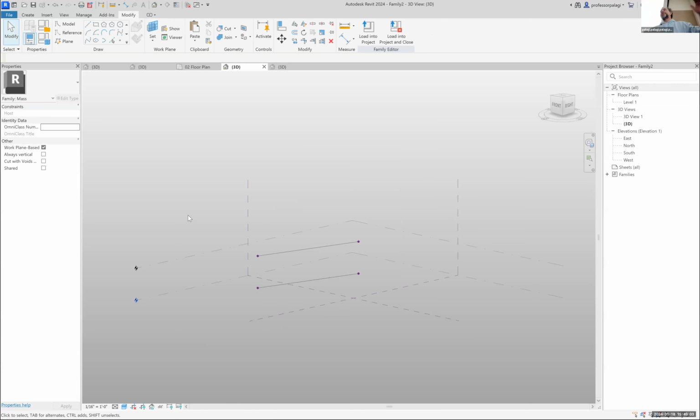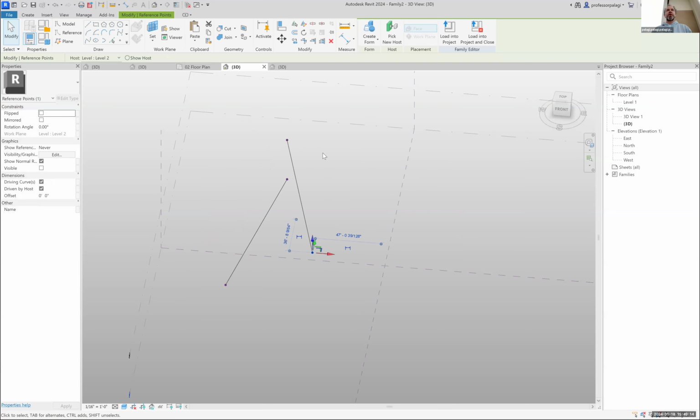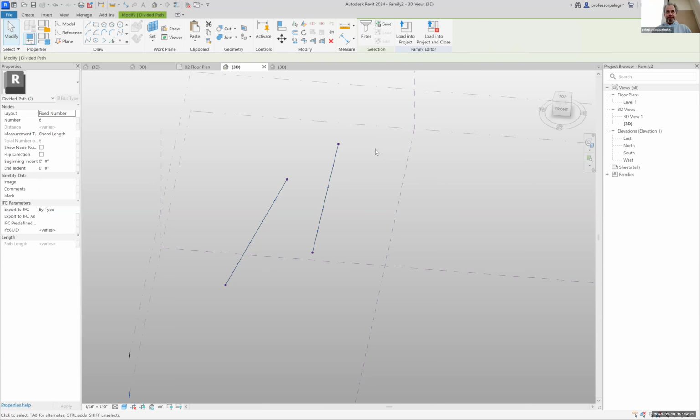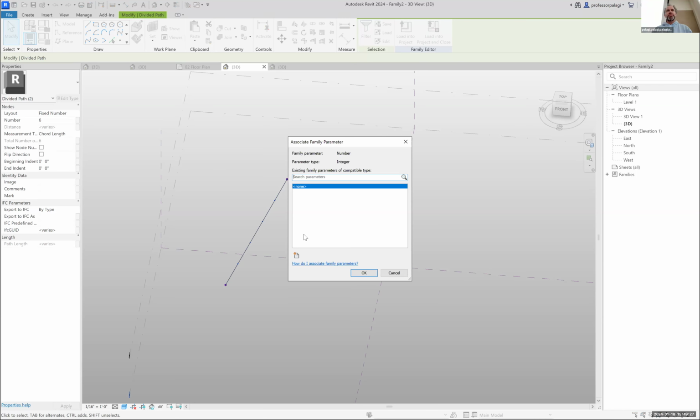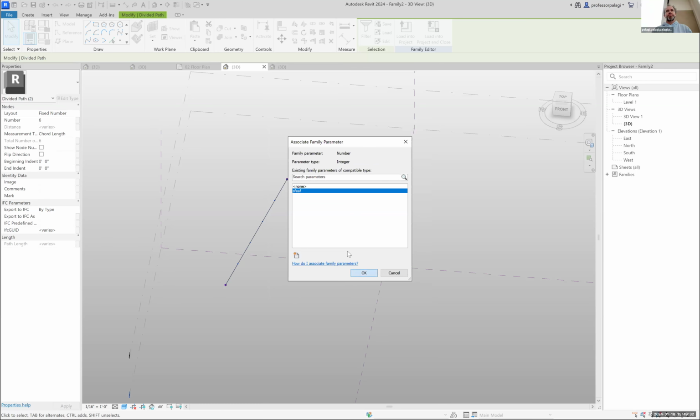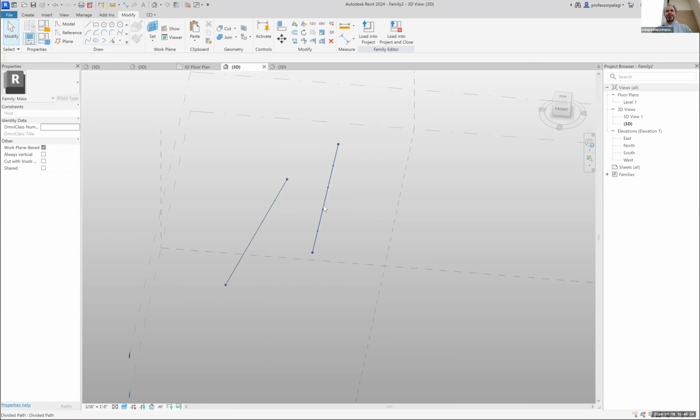You understand, like when you're doing buildings, right? You could say, hey, I want to repeat this on those 30 floors. Like that's how it's made to work that way. Anyways. Okay. It becomes really helpful when you're working out some things and you want stuff to line up the way you want. So nothing more than this. Let's divide the path. I drew them both the same way. Let's make this a parameter. Add a parameter, blah, blah, blah. Okay, now we can change that parameter, right?